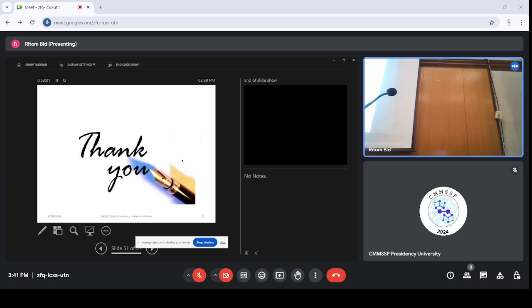Why is the efficiency so less? One of the problems is that when the light enters, a part of the light is getting reflected from the substrate surface. We have to choose the substrate accordingly so that most of the light should enter the device. Another problem is the substrate and then the material you are depositing. At the interface, there is a lattice mismatch, and that creates interface defect states. And they act as the trap center for the charge carriers. So they reduce the performance for the device application.